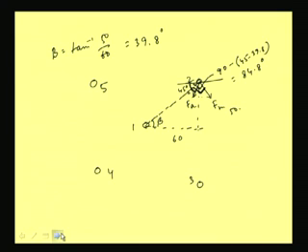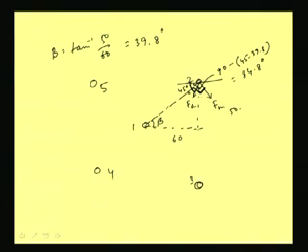This is one thing we need to know, because you have to calculate the FM. Another thing is for this rivet group: rivet 1 is not dangerous compared to 2 and 3, and rivet 1 will not exert any moment, so only FA will come. So, we will be focusing on 2 and 3. In case of 2, the angle between these two forces FA and FM is coming 84.8 degree. Now, let us see for rivet 3.